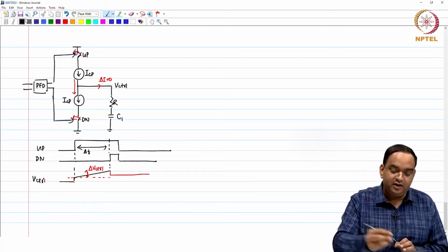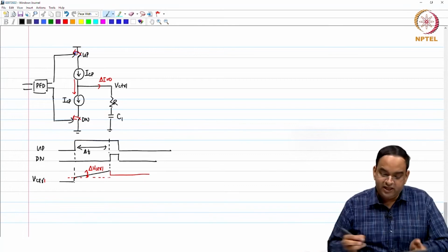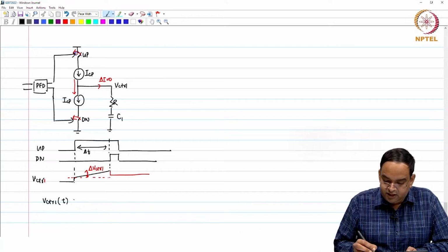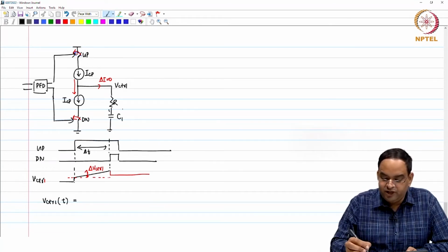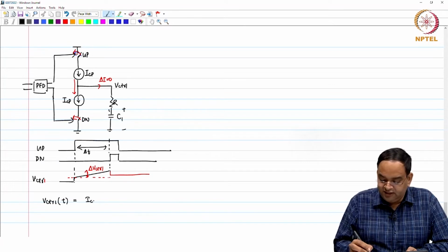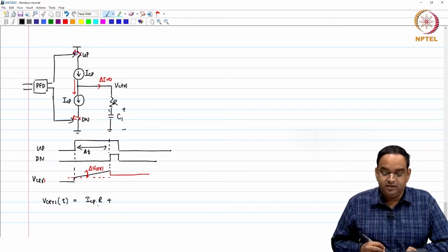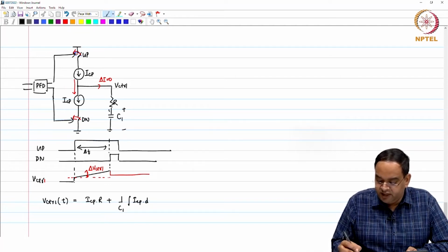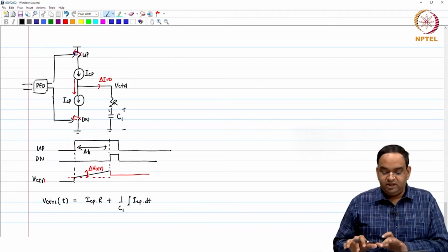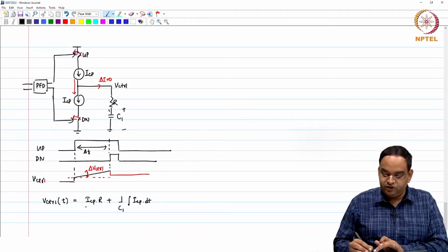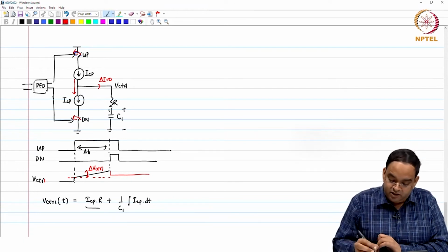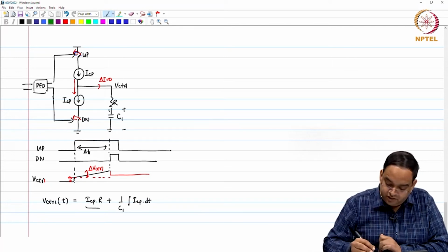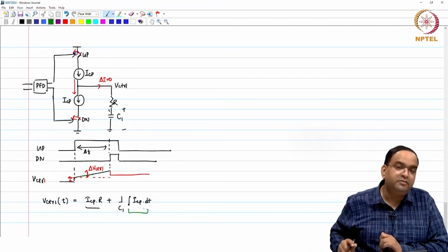the current directly goes through the loop filter. So, if I want to write an exact equation, I can write V control of t is ICP goes through R. So, you are going to get a voltage here. So, that is ICP R plus you are integrating current, right. So, ICP times dt. So, this appears to be a very simple expression. You see ICP times R, a jump here, and the continuous increase which you are seeing, right, that is this term.